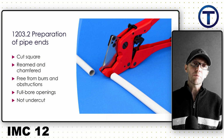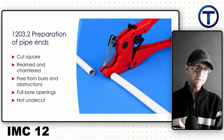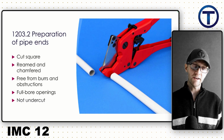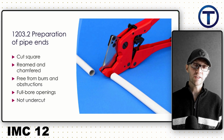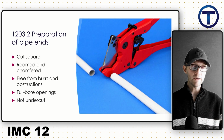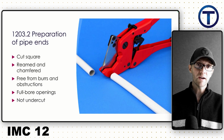1203.2 speaks to the preparation and the cutting of pipes. This specifically states that pipe ends should be cut square, they should be reamed and chamfered, free from burrs or other obstructions. They should have full bore opening. That means we didn't reduce the size of the pipe in cutting it, and it should not be undercut.